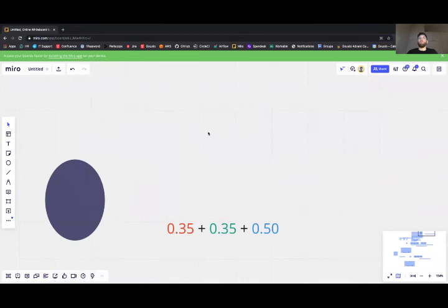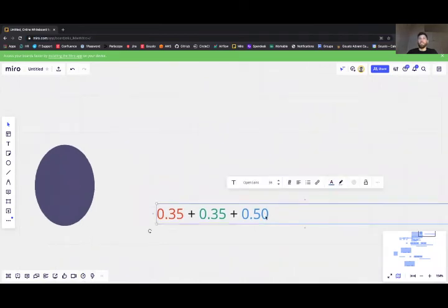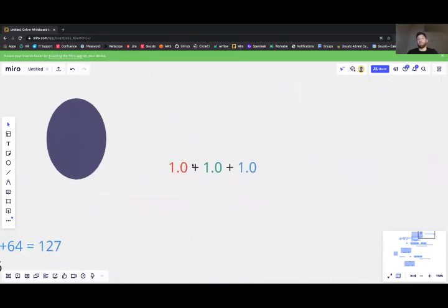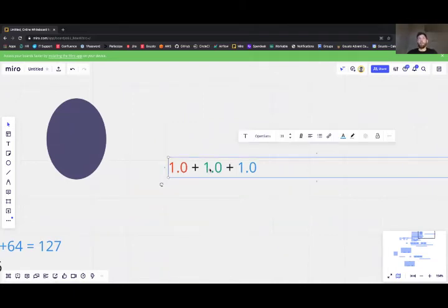Okay, and just one more example to discuss: max brightness white. So imagine this was 100% red and 100% green, 100% blue. That's the maximum brightness each of those channels can produce. Whenever they're mixed in equivalent proportions, you will see a shade of white or a brightness of white.